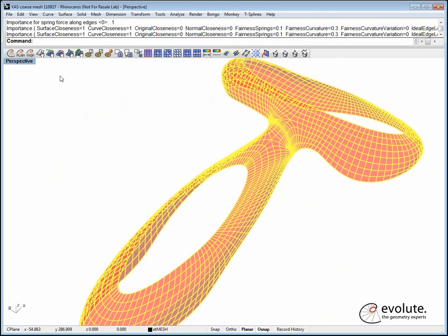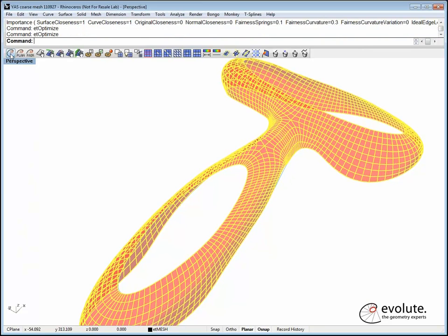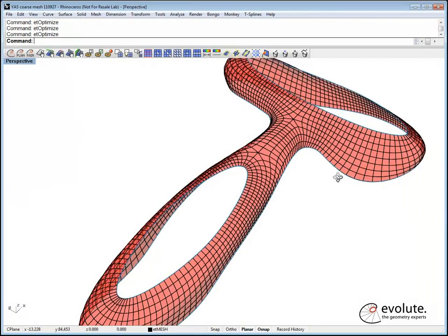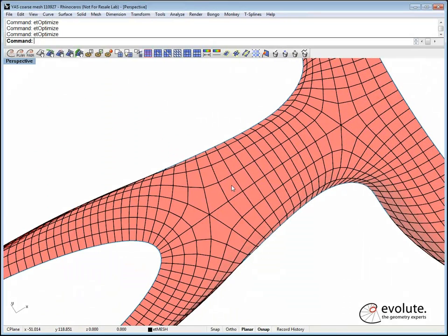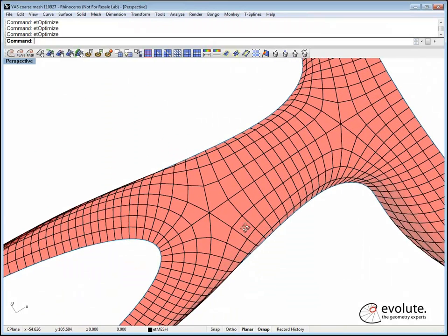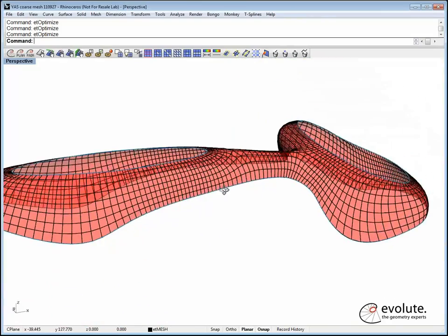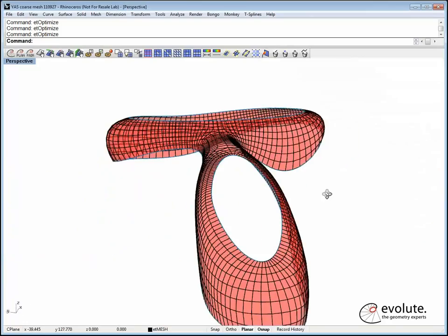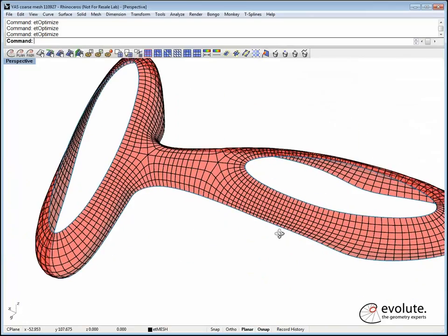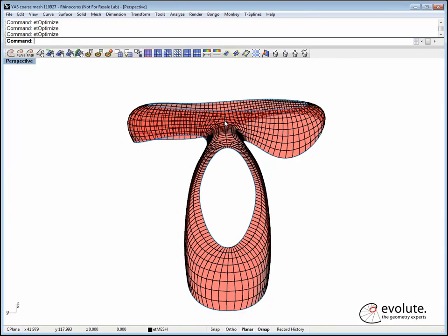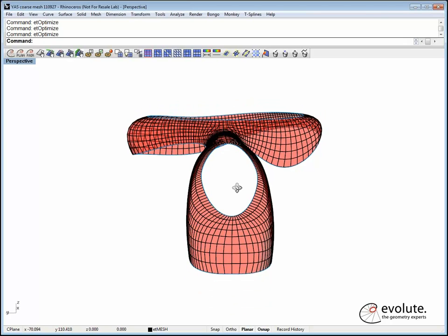Alright, so I set a bit of fairness springs there. This basically simulates springs between the vertices, and as expected it really relaxes this mesh layout onto your reference surface. Great. We have a good, nice uniform distribution of panels. We can again start with some optimization like putting all this spine, this row of vertices, in a plane. So let's select those.